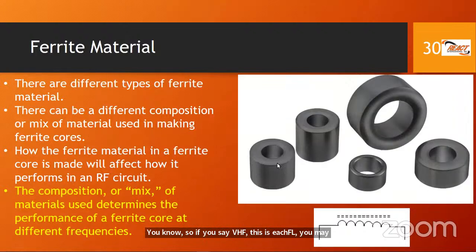So again, as a discerning amateur radio operator, you're aware of this. So you don't just go to Amazon or wherever and buy any old ferrite core. You will now be saying, hey, what mix do I want? So this is where the knowledge comes in. As an amateur radio operator, you are aware of the theory, and therefore you can be very discerning and selective, correctly choosing your components when you want to make, let's say, something to reduce stray RF in your shack, for example, or reduce interference. You know that the particular mix affects the performance on the particular frequency that you're using. All right.